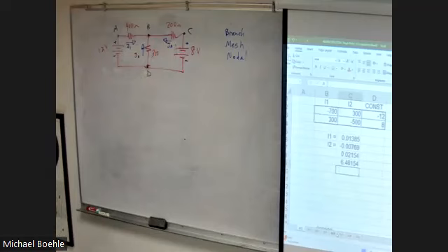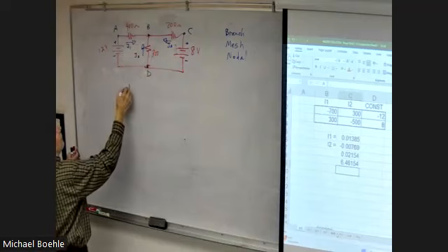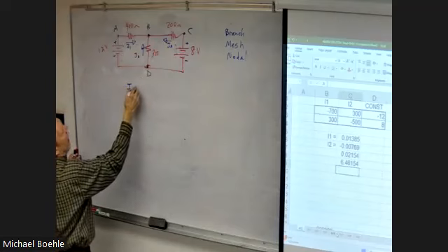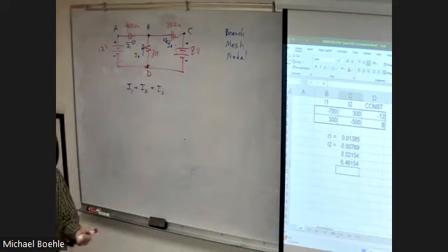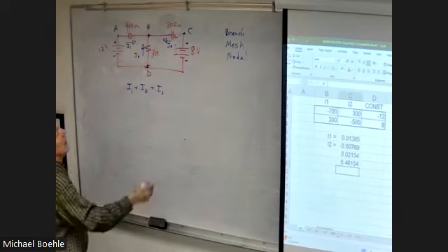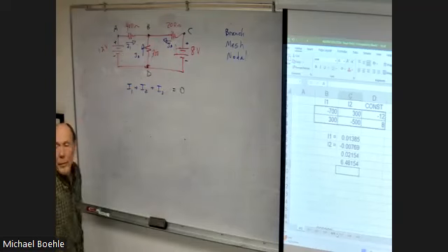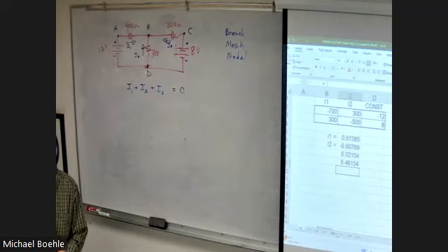So, by having those 3 currents, we'll set up our equation by saying what? Well, Kirchhoff's current law says the algebraic sum of currents at a point, since they're all coming in, they're all positive, equals 0. But here's the difference. I'm now going to define each of those currents based on the information in each branch.